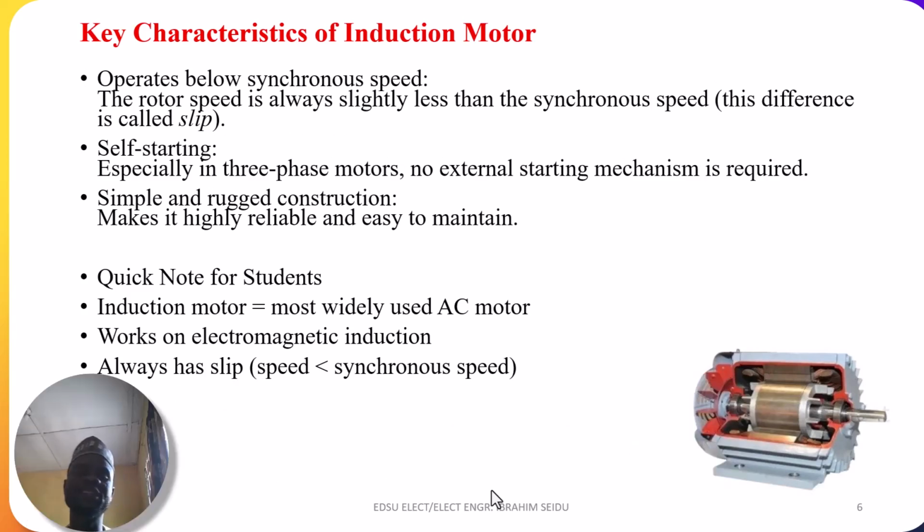Now, the key characteristics, or the key features, of induction motors. One, they operate below synchronous speed. This tells us that the rotor speed is always slightly less than the synchronous speed because it has slip. Then two, they are self-starting.